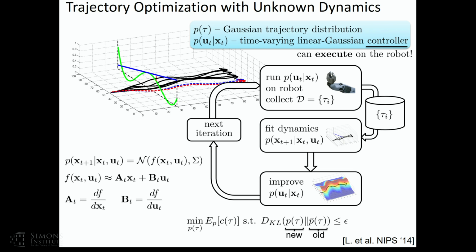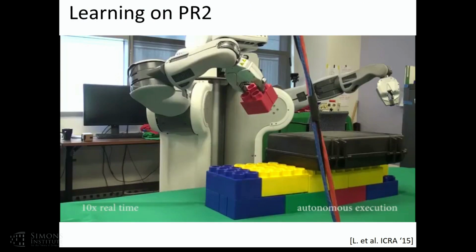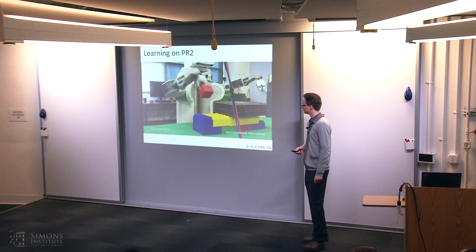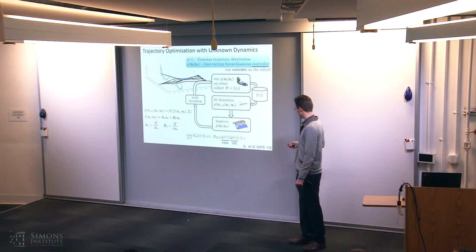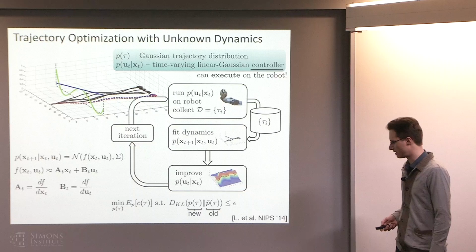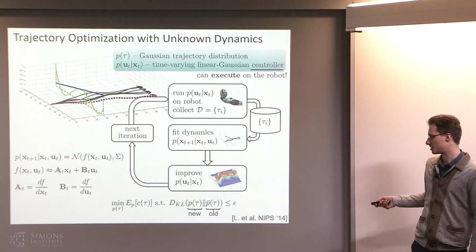So now we can do trajectory optimization, which means that we can plug this into our favorite imitation learning algorithms and use it to train some policies. How do you choose epsilon there? So epsilon, right now, we don't have a really good way to choose it, but we have a really good heuristic that dynamically adjusts it.